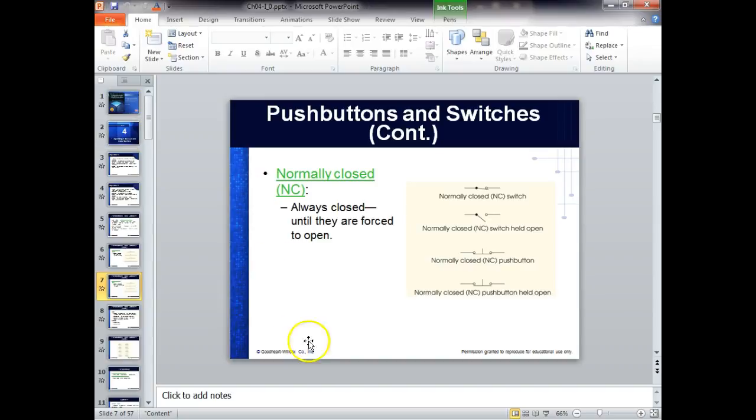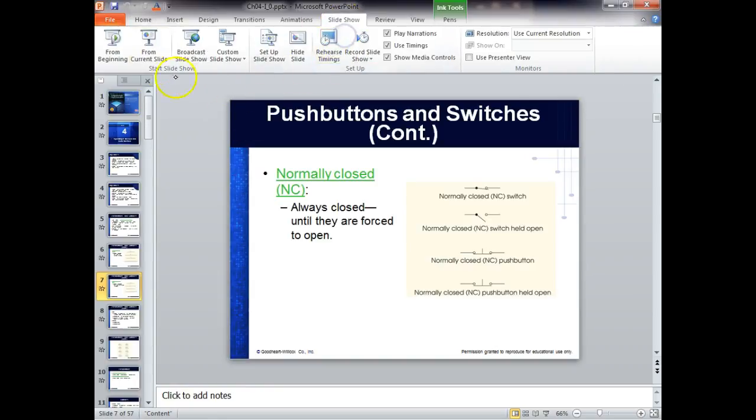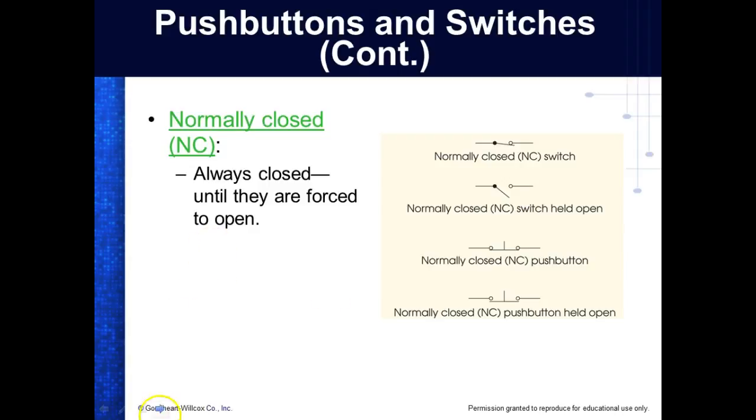Well, you do have to worry about negative and positive, because that is if it's a sourcing sensor. When we hook up something to an input port, normally we use one thing per port, right? You have all these inputs, and these inputs are going to have a common connection spot. The problem is we get used to saying common is the return. So I'm going to connect push buttons, and I'm connecting these down to L1. Now a common is just a common connection spot.